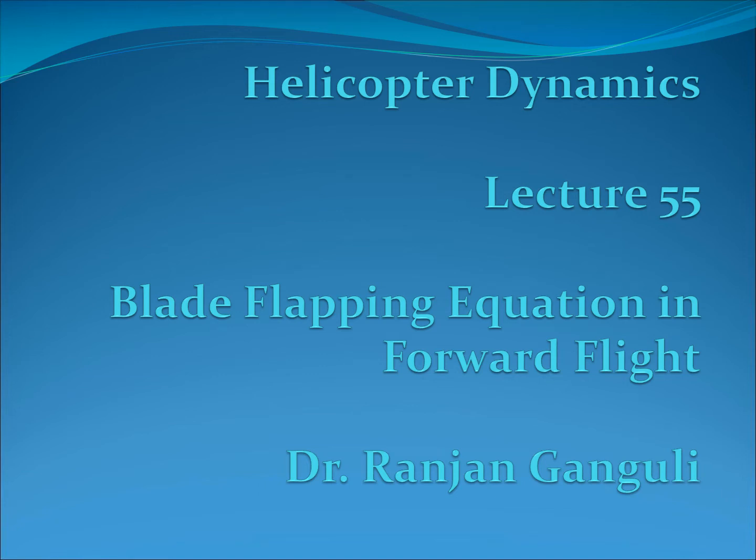Hi friends, welcome to lecture 55 of my helicopter dynamics class. And today I'm going to discuss the blade flapping equation in forward flight. So we are going to use the expressions we have derived using blade element theory, put it on the right hand side of the equation and expand it out.